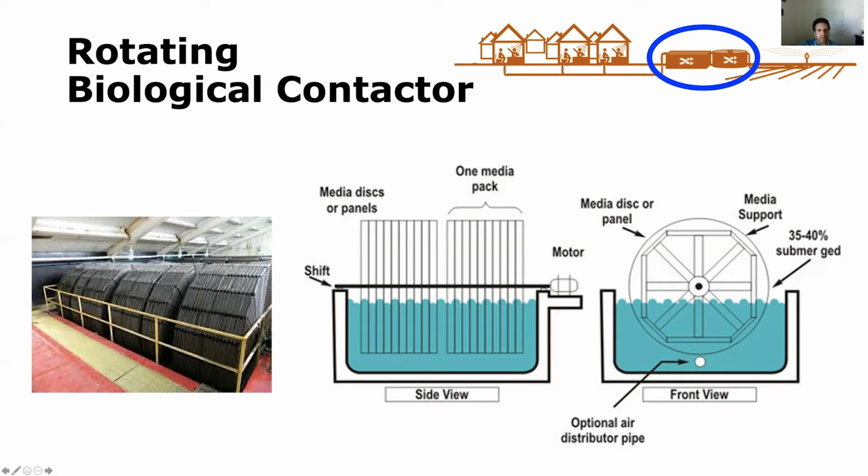So you have these large rotating wheels, and on the wheels there is some type of media, which again provides surface area for the microbes to attach to, and they form that kind of biofilm slime that you would see on any substance that's in contact with wastewater. Those microbes are cycled through the water. They're brought out into the atmosphere where they get re-aerated and back into the wastewater, where they're in contact with the organic material, and they're able to degrade that organic material down to CO2.